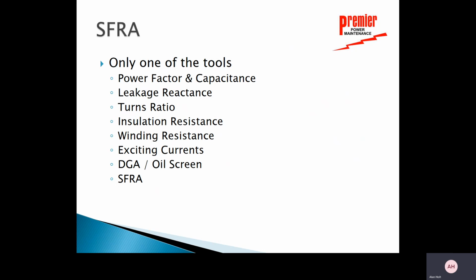So sweep frequency response, you're going to say, why don't we do that all the time? Why isn't that the only thing we do? Because that's not the only thing that we need to do. It's just one of many tools that we have. We have the power factor and capacitance test. The capacitance test on the power factor might catch some movement in the winding, but it might not. The power factor test is going to give you a good indication of the insulation properties inside that transformer and to see if there's any deterioration or any contaminants in the paper or the oil, and it's going to tell you of any kind of concerns as far as any kind of shorting or those sorts of things. So it's an important test, but it's in addition to the sweep frequency response.